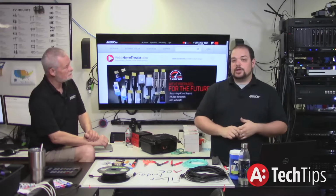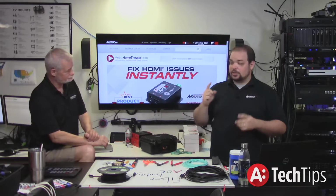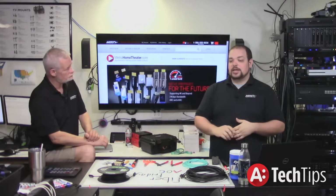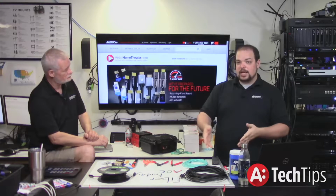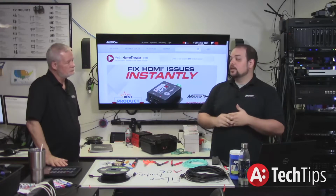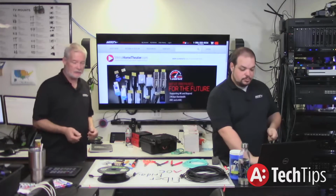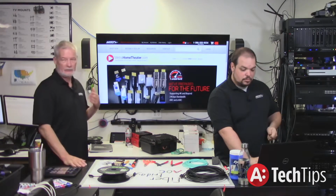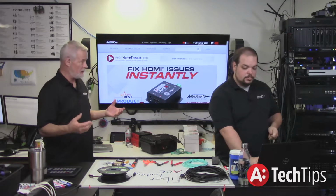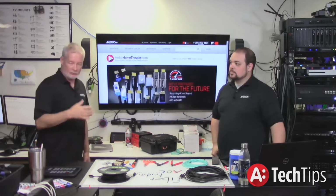When you're using an SFP module, you're either using a dual strand to go from one connection and back to the other, so you get a transmit and a receive, or you're using a single line in that connection. With our fiber HDMI cables, we're using 4 strands, and we're only using 6 gigs currently per strand. That is limited not by the fiber, but by the electronics in each head shell. When people talk 40, 60, 100 gig, what they're referring to is very expensive electronics that go to either end of the cable. That effectively would put a product like this completely out of the marketplace because of the cost.